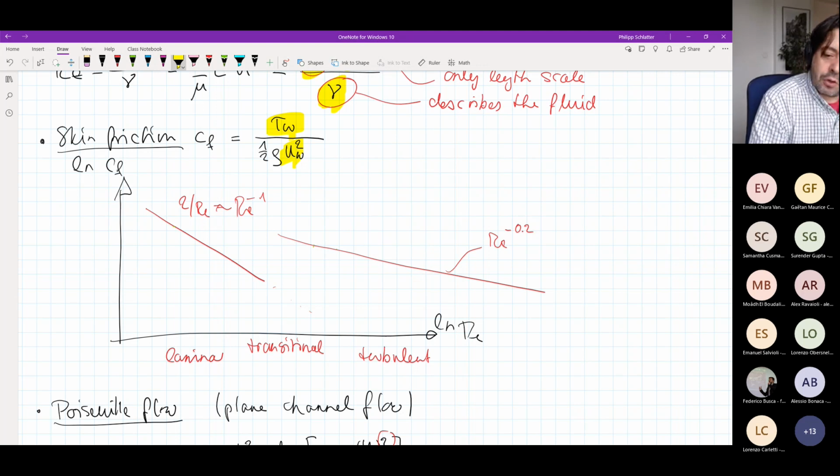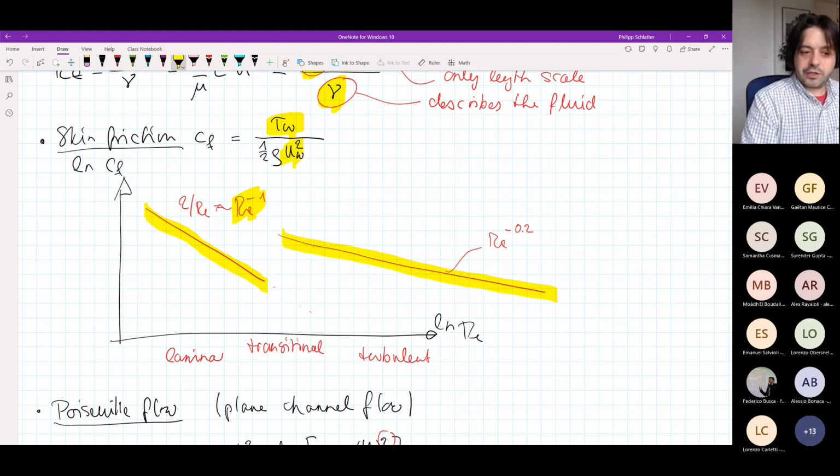And then what we saw is very similar to the Moody diagram. You have behavior like this in the laminar flow, very typical that you get a skin friction which is proportional to 1 over the Reynolds number. And then once the flow has become turbulent, the skin friction at a specific transition location or transitional Reynolds number will jump up a little bit.